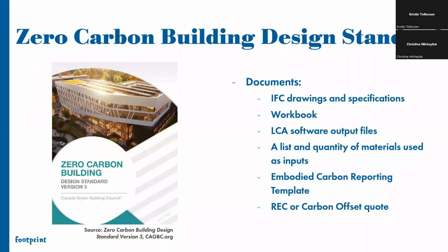Later we'll briefly discuss Athena Impact Estimator, which is a product that actually has a file, but there are online programs like One Click LCA, in which you may just need a list and quantity of the materials, like a bill of materials. There's also an embodied carbon reporting template. And as I also discussed, a carbon offset quote is required, and the number that comes from your embodied carbon assessment would need to be part of that as well.